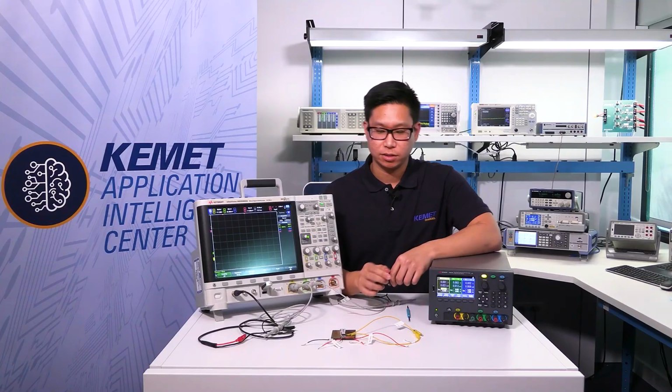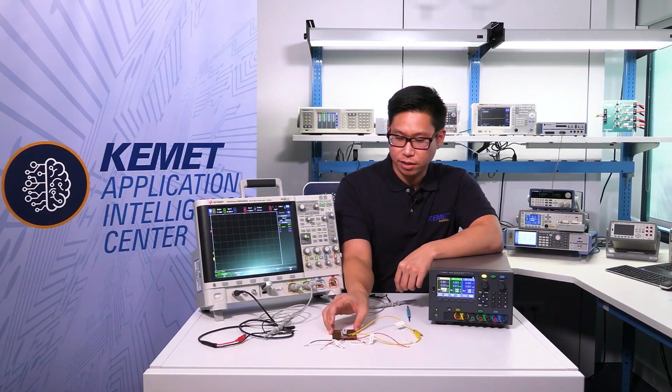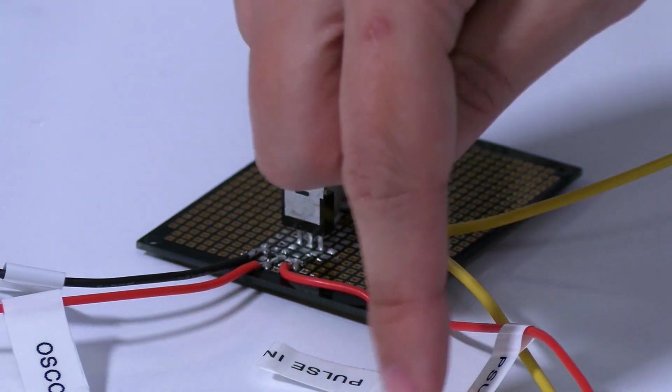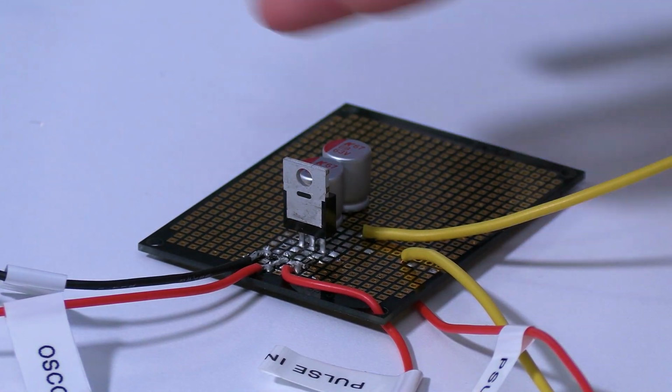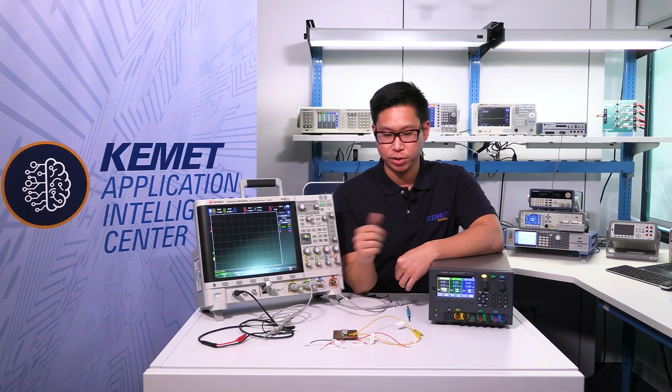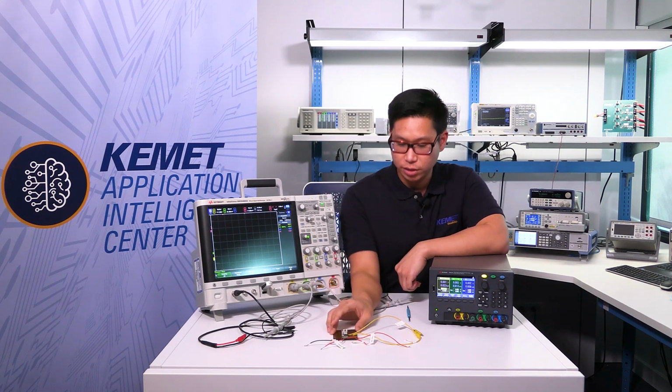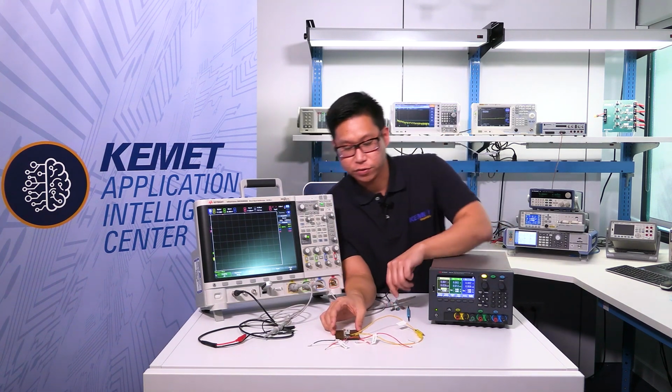Yes, so over here I have a circuit that allows you to put in a pulse input. So we're going to saturate the inductor by periodically putting in a pulse. And then during that pulse, the current's going to ramp up. And then we can define the saturation current by how the current curve looks on the oscilloscope. So for this experiment, we're going to need a power supply, an oscilloscope, and a board. So let's take a look at the board first.